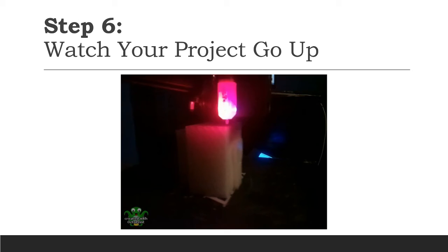So first step is actually taking it off of the print board here. Now the trick is to make sure that you have a good grip on it and pull it from the corner. See, it just came right off. And see, it's nice and smooth on the bottom. You can kind of take some of that away. And now the next part is going to be taking all these supports off that we have here, here, and right under the logo there. So I'm going to go show you how to do that somewhere else.